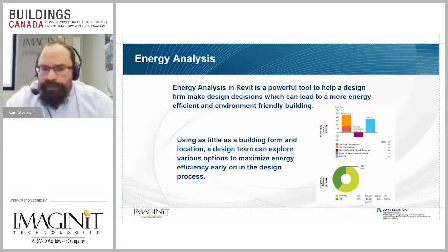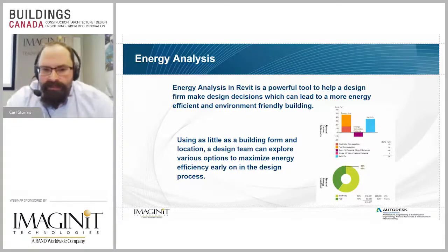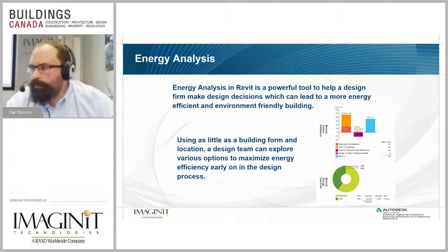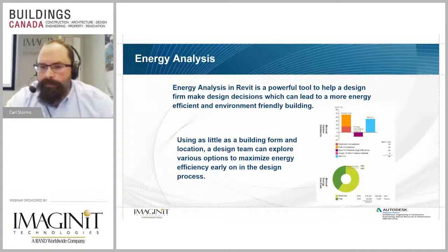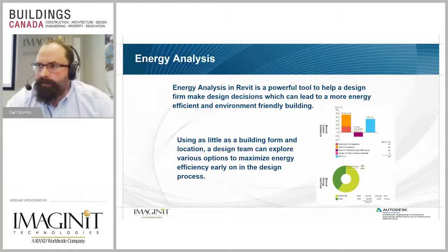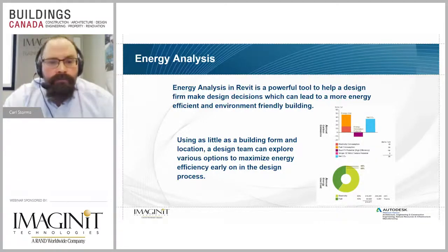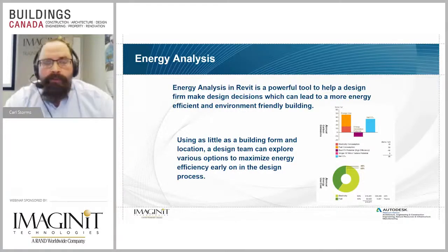And just to be clear, when we're working with Revit, as we're doing energy analysis inside of Revit with the out-of-the-box set of tools, we have sort of three solutions that we can look at. We have conceptual analysis, which we'll take a look at a little bit later on in this presentation, where simply we can start with masses and get a real high-level understanding of how our building is going to perform. As we're going through conceptual design, working our way into design development, perhaps even starting down the construction document workflow, we can get into building element analysis, which just takes the actual elements as opposed to a mass and starts doing some energy analysis in that form.